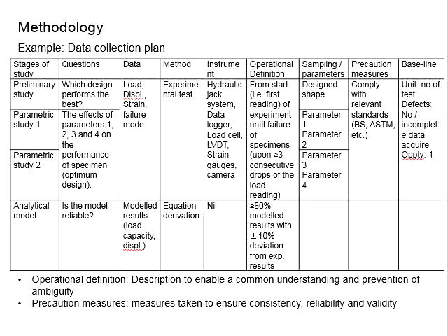Don't forget that if you are dealing with concrete, preparing the specimens is one thing. You spend some time to acquire the material, fabricate the specimen, maybe for 1 to 2 weeks, cast the specimen, and then you need to wait for 1 month for the specimen to harden, reaching the mature age before you can proceed with the testing.